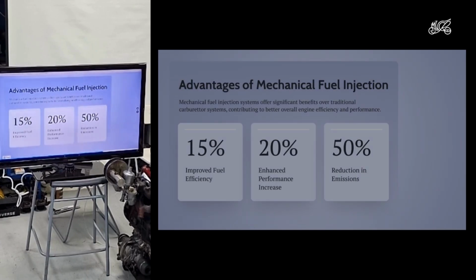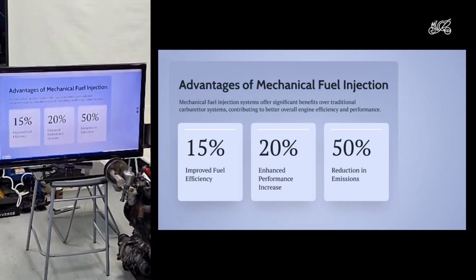And because you're controlling that mixture, back on that chart at the start, you're controlling the mixture better, the emissions are better. So a win everywhere, but it's more expensive. It's more expensive than a carburetor. And ultimately, mass market automotive is driven by cost. And so you only really saw this on performance models. It never really got into mass market because of the cost structure. That's why beasts like this existed in the 1980s and 1990s, because that's, believe it or not, cheaper than an injection system.